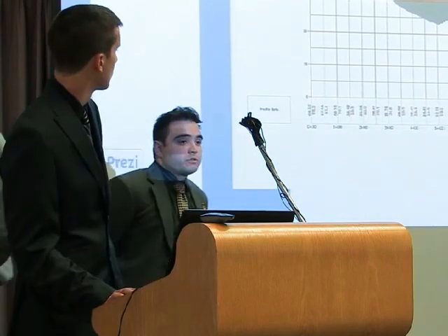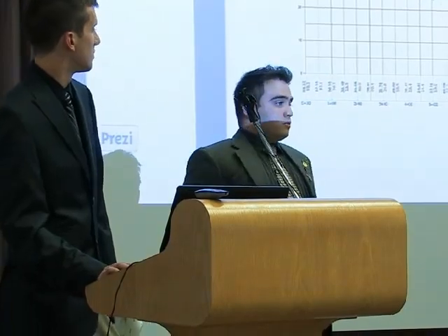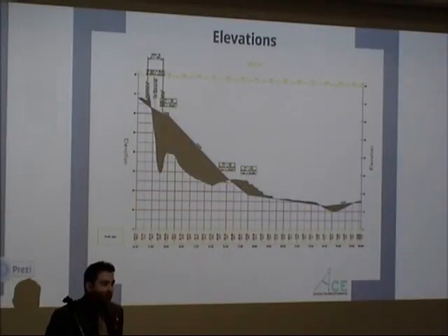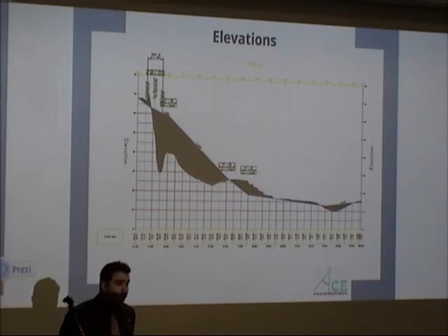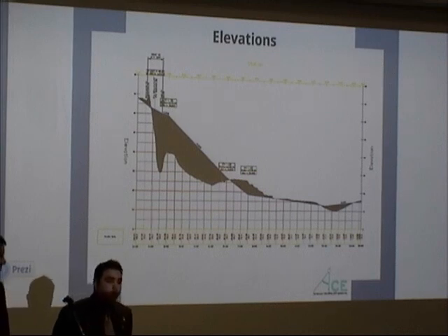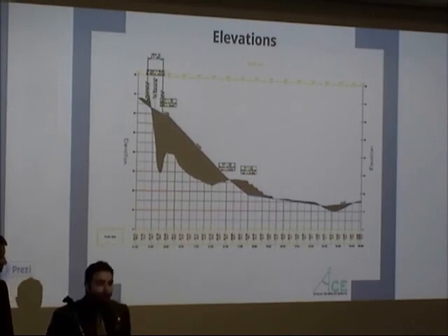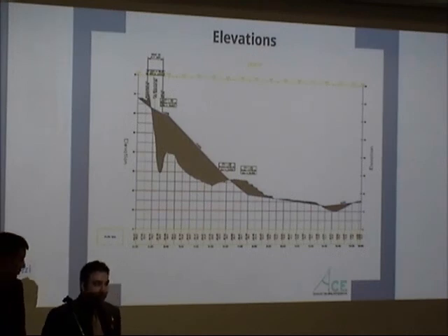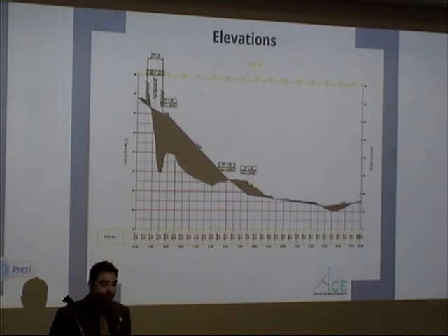Thank you, Sam. My name is Luis Gonzalez, and I'm here to talk about the elevation changes on the road. When we decided to draw the alignment here, we decided to have a critical point on the intersection of the first entrance of the parking lot at 18.5 feet. Using the 6% grade coming from the existing Schooner Drive, we had to dip it down even lower to an 8% after we go past the bridge. At station 600, we changed it to 6.04% until it meets 80.5 feet in elevation at station 750.